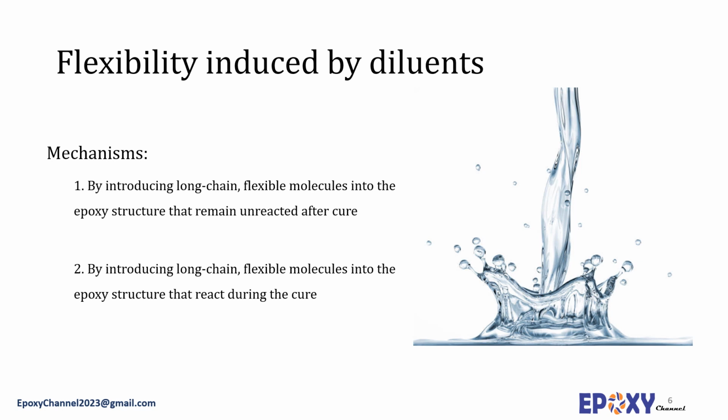As flexibilizers, these diluents are often blended with the more reactive epoxy resins. The commercial flexibilizing reactive diluents are predominantly glycidyl derivatives like glycols, dimerized acids, or reaction products of dicarboxylic acid with epoxy resins. Modern flexibilizers to modify diglycidyl ether bisphenol A base include isocyanate monomers and prepolymers, silicone polymers containing amine termination, acrylic polymers with carboxyl termination, functional liquid polybutadiene derivatives, carboxyl-terminated butadiene acrylonitrile polymers, etc.